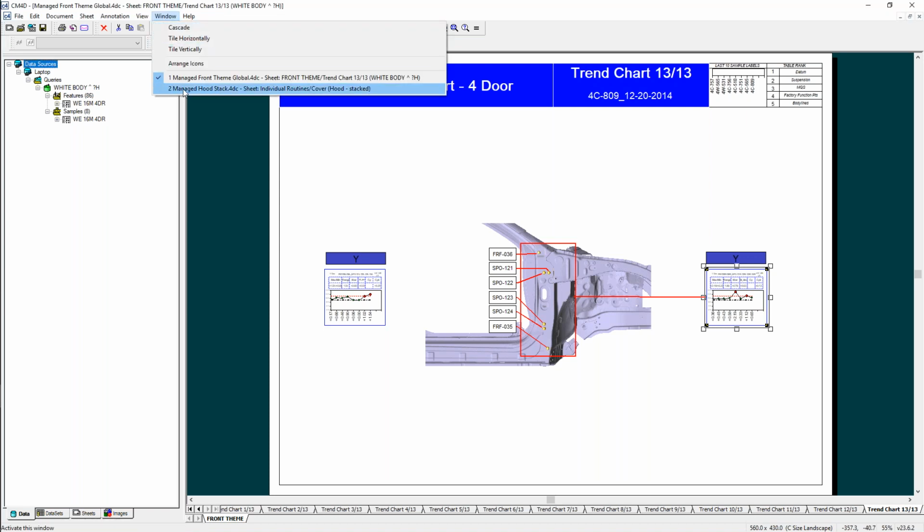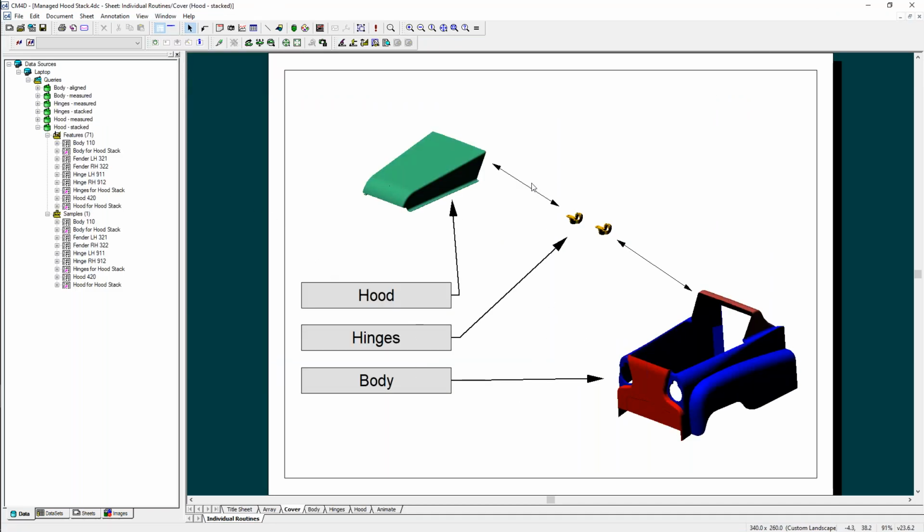So as an example, what I mean is that we can take individual parts that have been measured and predict how they would fit together by putting them all within the same alignment scheme and also adding the deviations from the values in one alignment to the part that fits on it within its own alignment, therefore seeing the total amount of deviations that exist for your points for a final assembly.